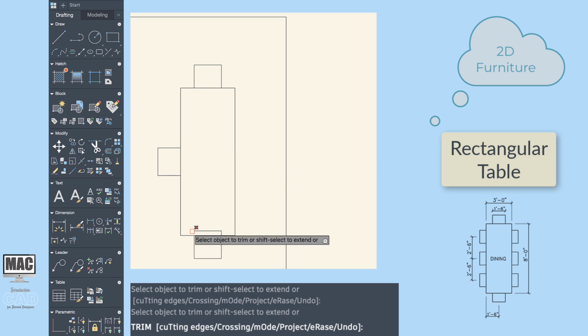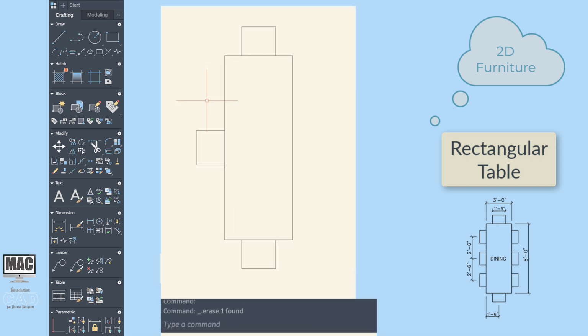We will use the Copy tool again to do a little precision space planning. Make sure the Ortho Function 8 key is toggled on. At the command line, type CO, enter. Pick the dining chair on the left side. For a first point, select the midpoint of the vertical line segment of the chair.